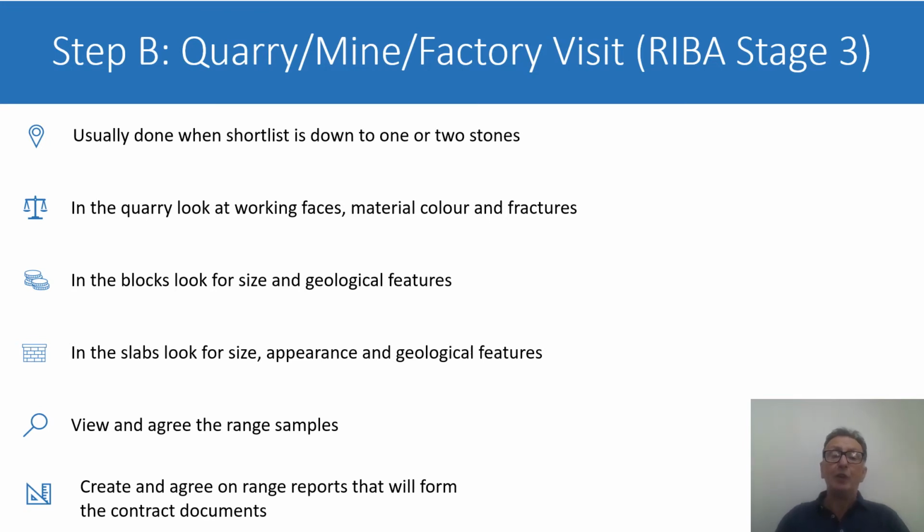This visit allows you the opportunity to view, and often in coordination with the client and his representatives, agree the range in the appearance of the stone that you want for the project. It's always important to create and agree the range and document this in a report wherever possible. The maximum benefit from a range report comes when it's included as part of the contract documents.